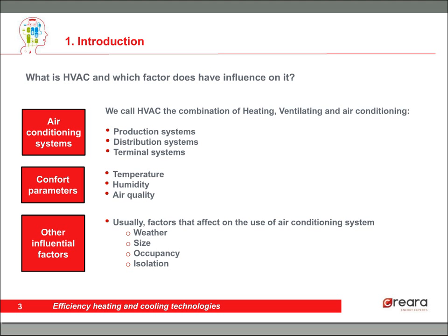Well, you might be wondering why the weather, for instance, or the temperature can affect the energy efficiency ratio of, let's say, a chiller. Let's put an example here. Imagine a chiller in Cordoba, in the southern part of Spain, and imagine it also in France. Well, apart from the fact that in France the chiller is going to work much fewer hours than in Spain because of the weather and the outside temperature, the energy efficiency ratio is also going to be much higher in France than in Cordoba.